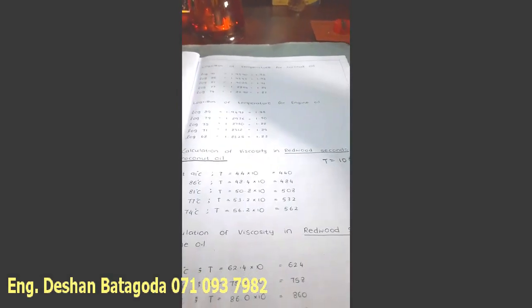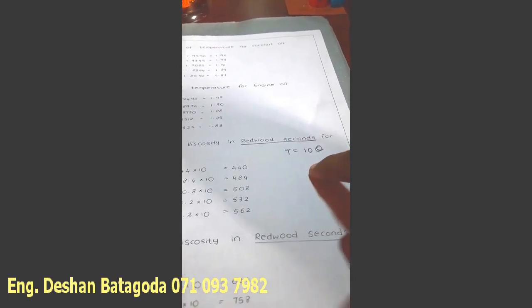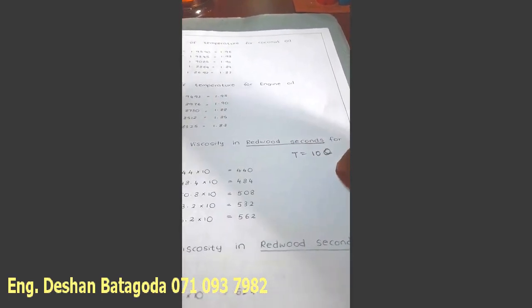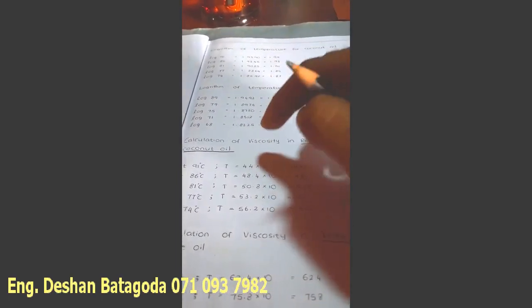Okay, so now let's see how to do the calculations. We are going to calculate the viscosity in Redwood seconds for coconut oil. Here we are going to use an equation, T equals 10 theta, right? What is theta? Theta is the time taken to collect 50 cubic centimeters of the liquid, that means the time taken to collect 50 cubic centimeters of coconut oil. We know the value of theta for certain temperature values.